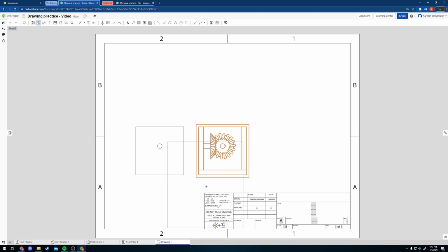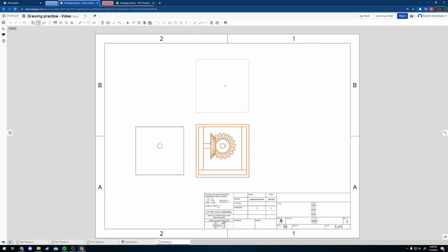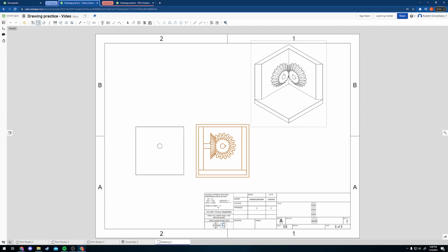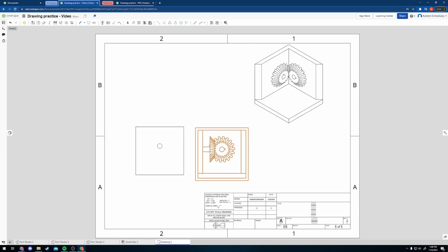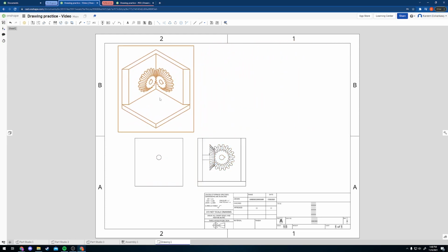So if I click here, now if I move my mouse to the right again, it's going to rotate the camera to the right. If I go up and to the right, it's going to show you an angled view. If I go just above, it's going to show me a top-down view, etc. And you can just play with it, and you'll see it'll show you all the different views from this. This makes your life much easier. So I'm going to go up and to the right, and click. Now I have an angled view. So now you can press Escape to deselect the project tool, and now you can move around your parts, and you can put them wherever you'd like.